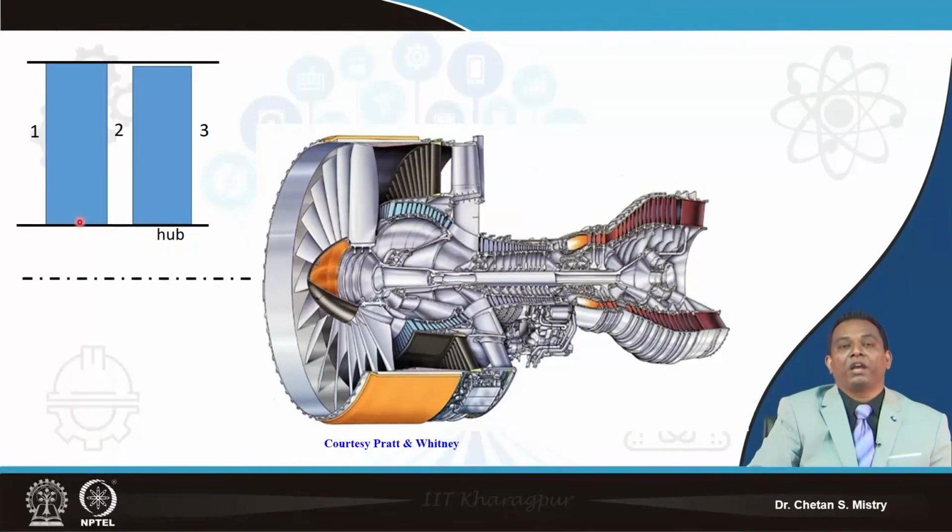But here, this represents my fan. And for the fan, my entry area and exit area come out to be different. Why? Because I will be having a rise of pressure. When I say rise of pressure, at the exit you will have a rise in density. And according to continuity, my continuity at entry and exit must be satisfied.